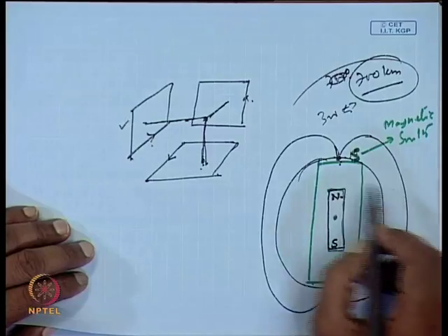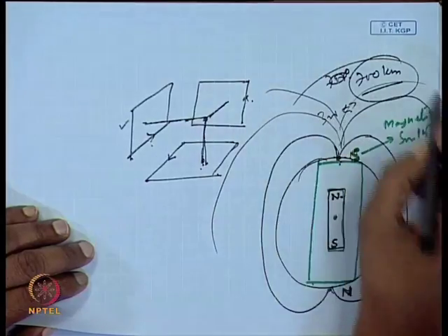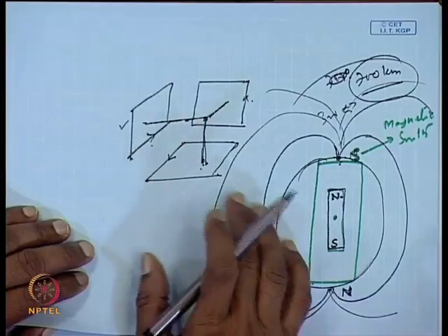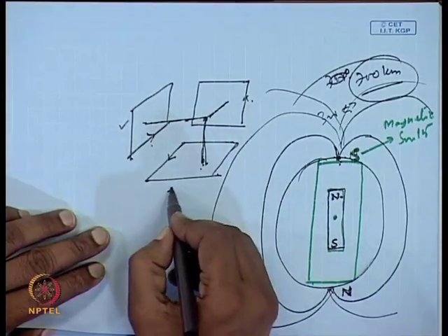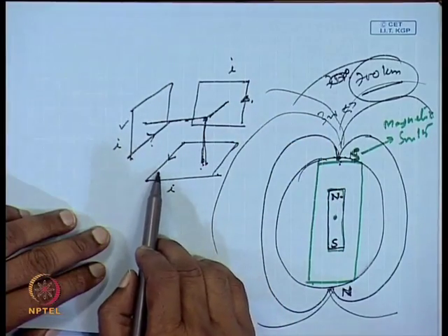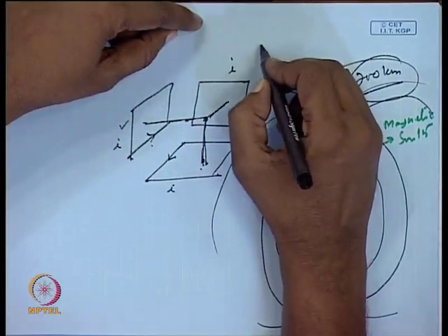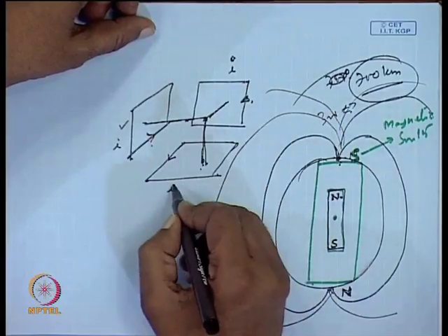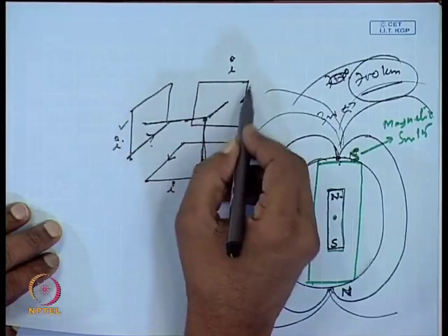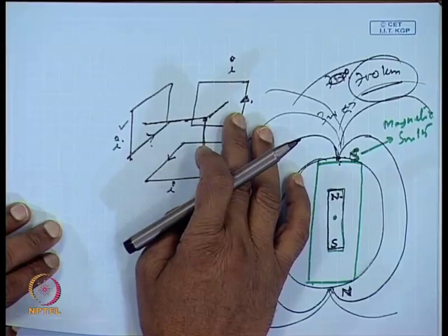In this magnetic field, if your satellite is moving, you have the magnetic field spreading like this, and let us say coming and terminating over this pole. These coils are interacting with this field, and they are carrying currents, so they will produce a dipole moment. These coils act as a dipole, and we are not going to get into the equations for them, but you assume that these are acting as a dipole, and therefore, once they interact with the magnetic field, a torque will be produced.